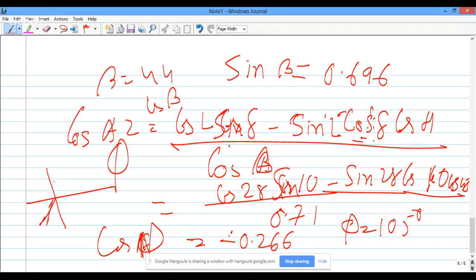So it would be somewhere here, 105, because 90 degree plus 3 p.m. So it will be somewhere in the afternoon. If the wall is in the north direction, then of course the wall solar azimuth is 105 minus 90, so that would be 15 degrees. If the wall is south facing, it is 180 degree with the north.